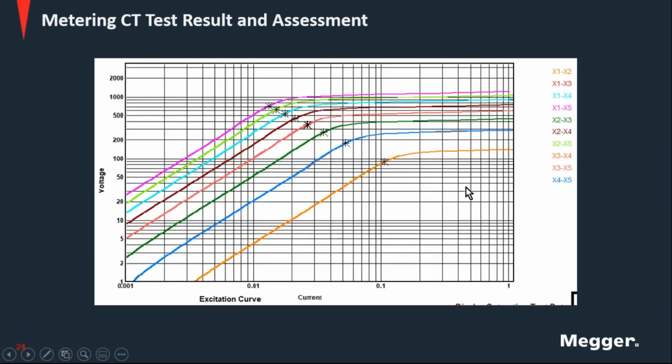What the security factor tells you is, for a particular overload, say 10 times, 20 times, or 5 times the nominal current of the CT on the secondary, what is the cutoff point that you want on the error. And the error on the CT, as Volney showed, is the excitation current.